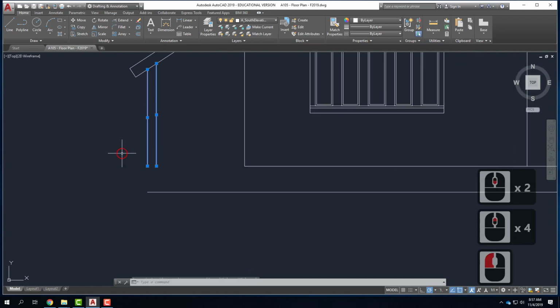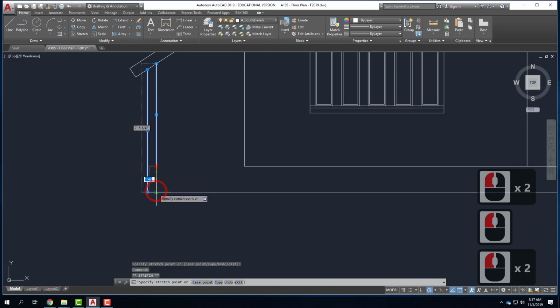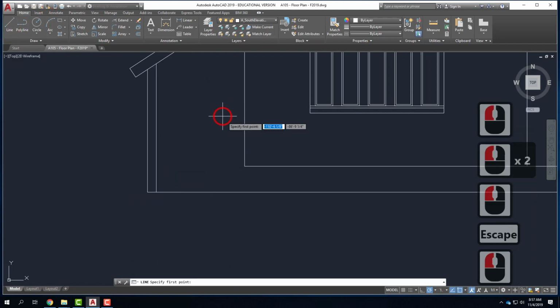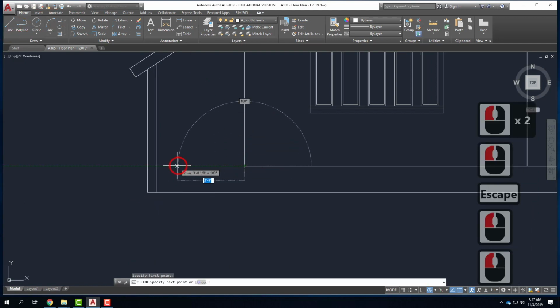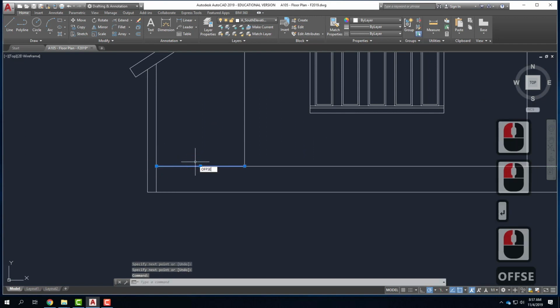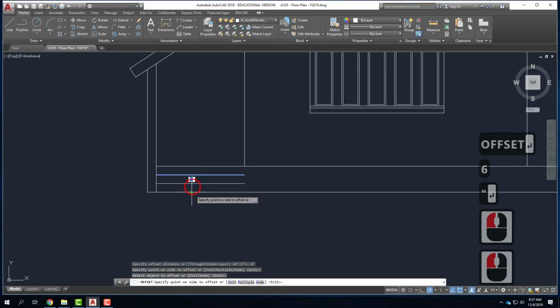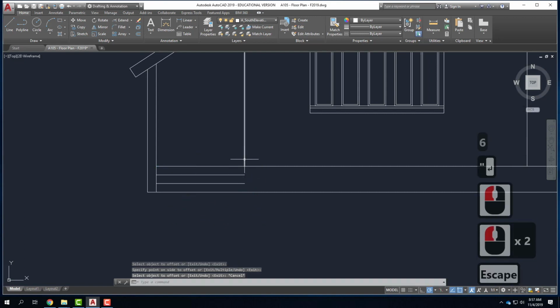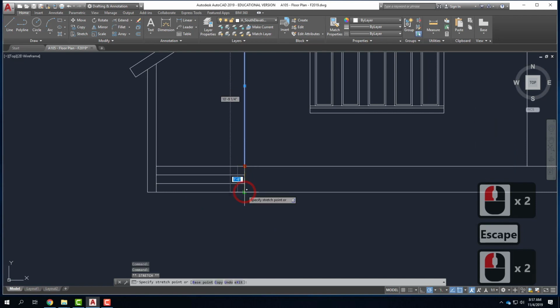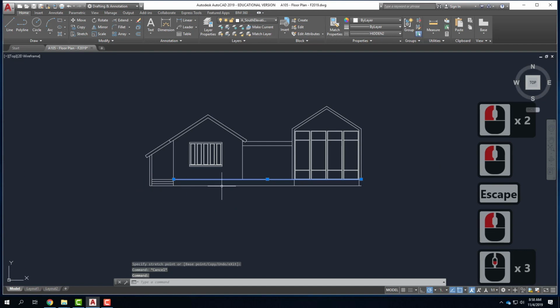This one had some stairs coming up to it, so let's pull this all the way down, like that. I've got the finished floor height that we would see here, and then I've got some stairs. So I'm going to offset these. I'm going to do them generically at 6 inches. So there's one stair, there's a second stair, etc. This edge of the building would come all the way down. We already have this piece as hidden because it's the floor height.